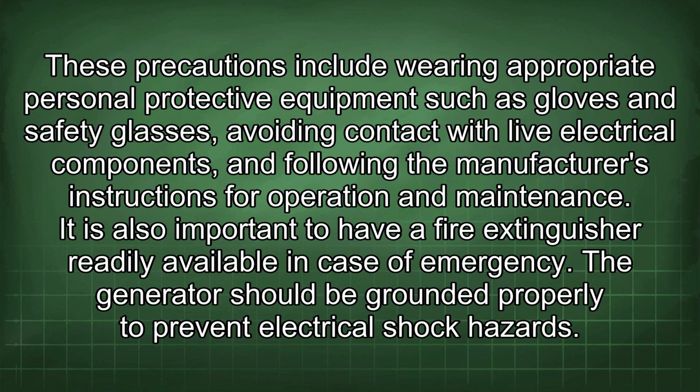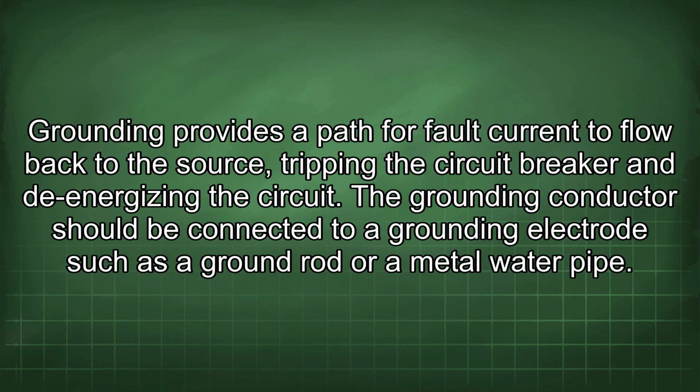It is also important to have a fire extinguisher readily available in case of emergency. The generator should be grounded properly to prevent electrical shock hazards. Grounding provides a path for fault current to flow back to the source, tripping the circuit breaker and de-energizing the circuit.